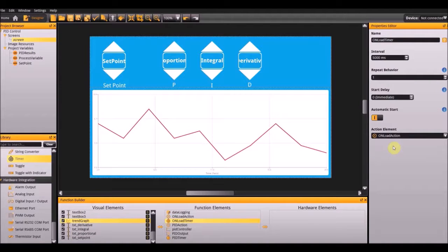The next function element we are going to create will tie the up and down arrows with the numbers and the rectangles in between them, and that will be tied to the PID controller. The first group of elements will be for the setPoint up arrow. We will first need to create a math builder, which will allow how high we can select the number and the rectangle to be, and by how many digits it will change by. So add a math builder to the project.